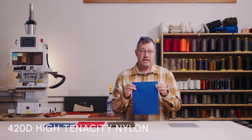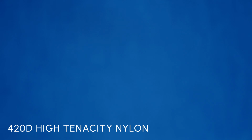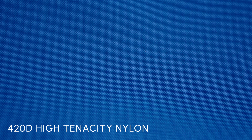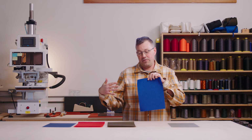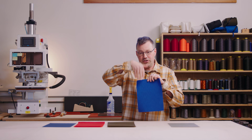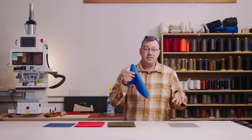This is our 420D high tenacity nylon. This textile is balanced woven, which means that the frequency, or number of yarns, in the warp and the frequency of yarns in the weft is identical. So the yarns per inch in both directions is the same. So the structure of this is identical, whether we look at it 90 degrees or not, it's even all the way through. So that was a 210 that we looked at.